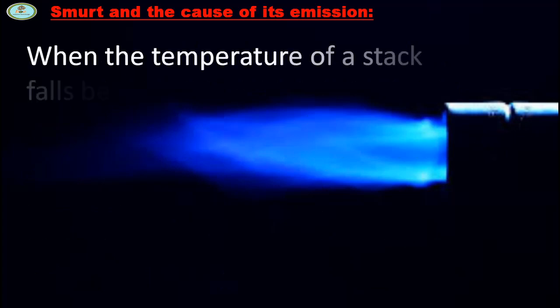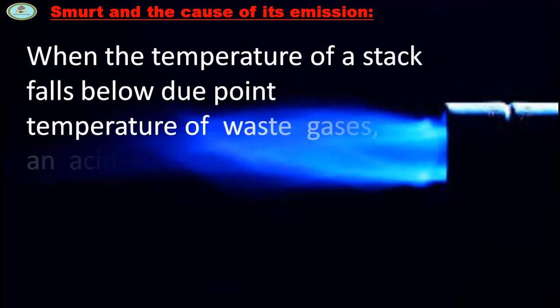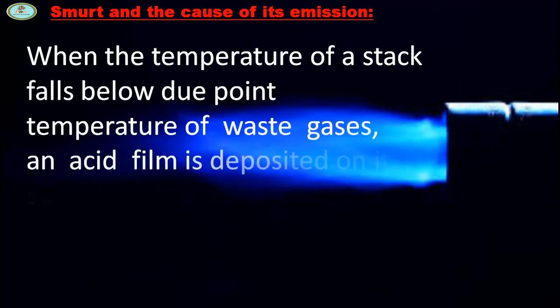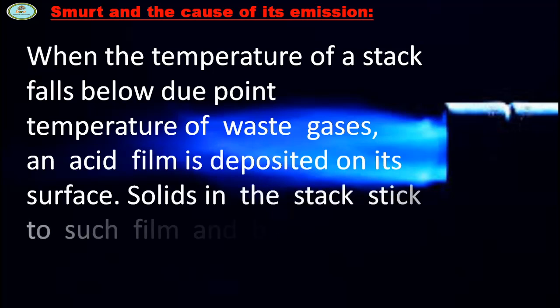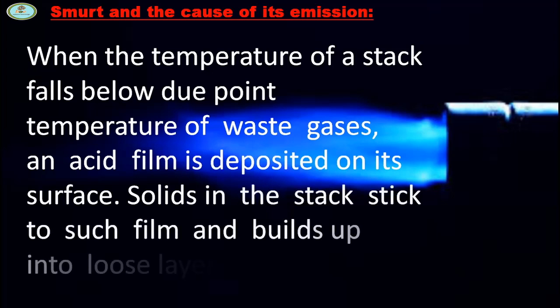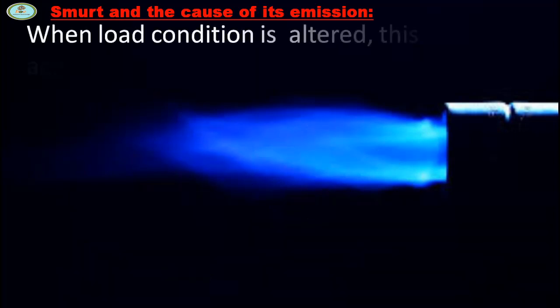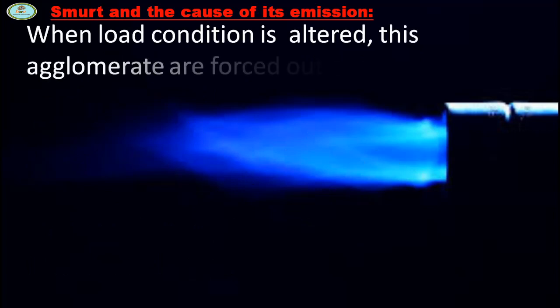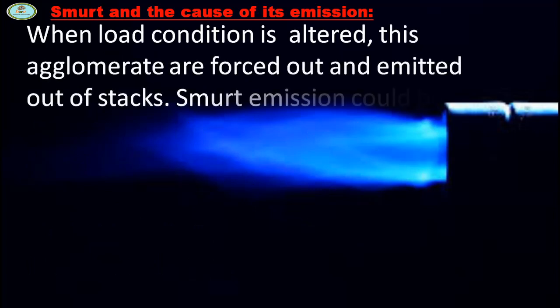When the temperature of a stack falls below the dew point temperature of waste gases, an acid film is deposited on its surface. Solids in the stack stick to such film and build up into loose layers. When load condition is altered, these agglomerates are forced out and emitted out of the stack.